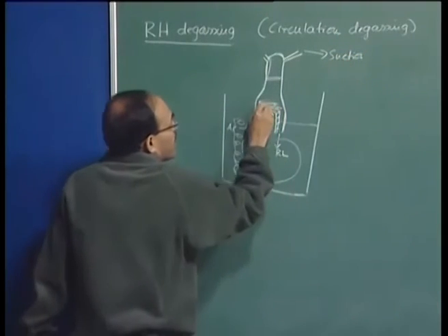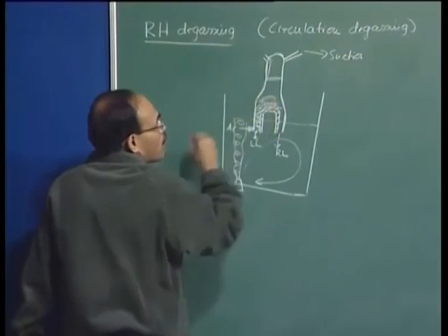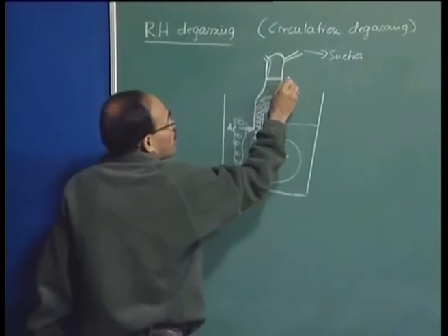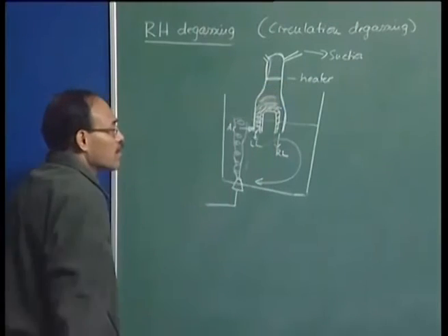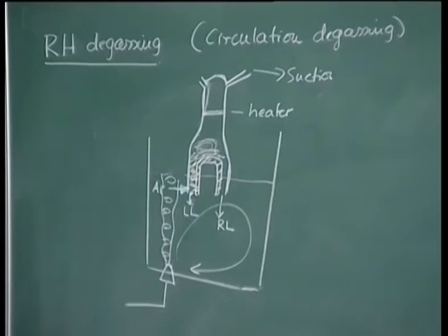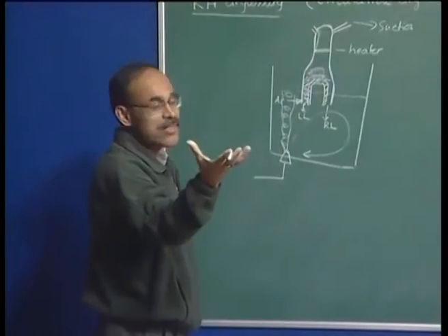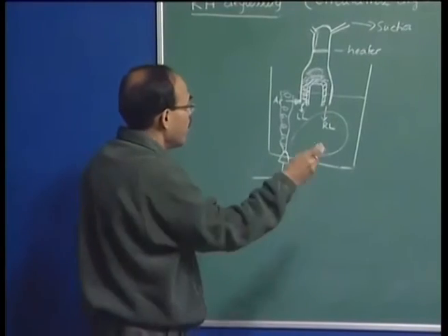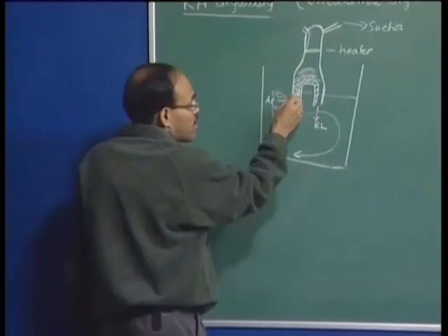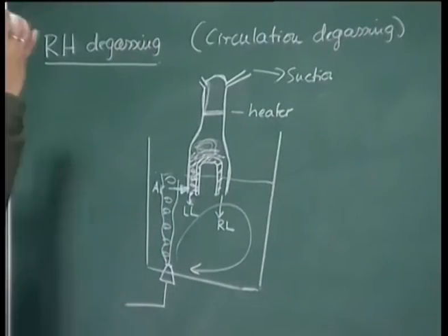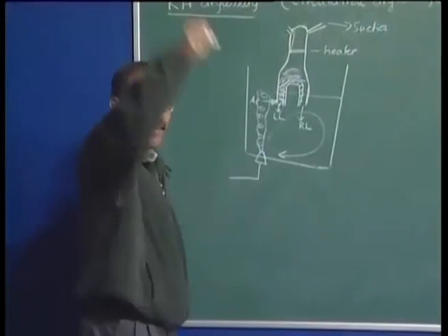So, the molten material here is all exposed to vacuum, and this is the plate which may be acting as a heater to supply heat to the molten metal, because I said that there is going to be a significant amount of temperature drop. So, the bubbles injected here are going to increase in size because of the application of the vacuum, and as these big bubbles rise with extreme rapidity, they are being drawn by the high pressure at a very fast rate.